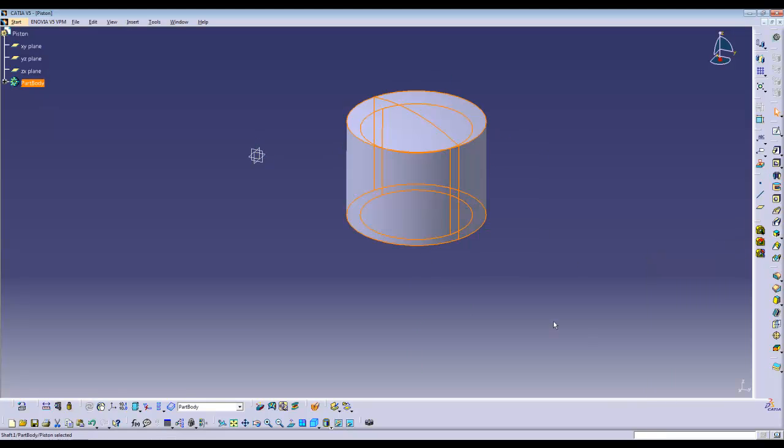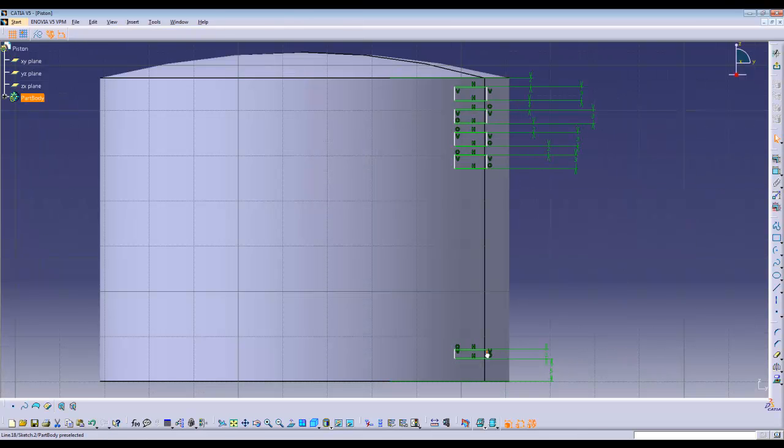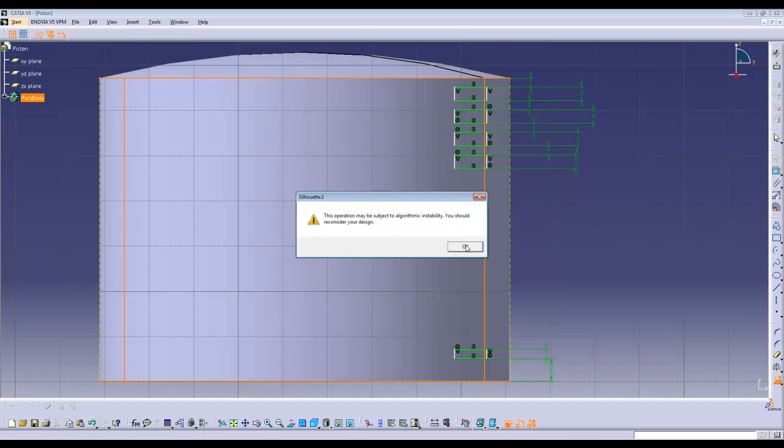Using the revolve command, select the axis as shown. Enter into the YZ plane once again and create 5 squares. Use the constraints as shown.